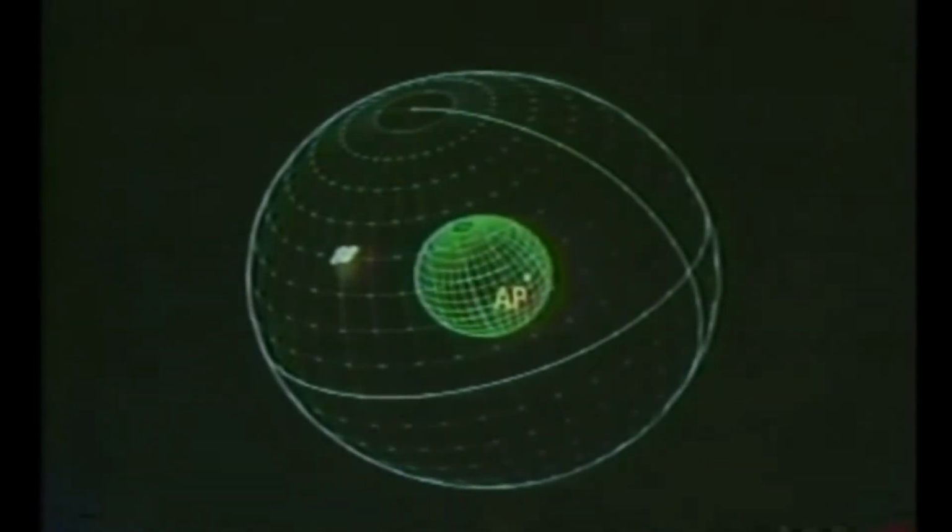Then you assume a position for yourself on Earth, somewhere near your DR position. In the intercept method of celestial solution, you determine and locate your actual line of position relative to your assumed position, instead of the GP of the celestial body.